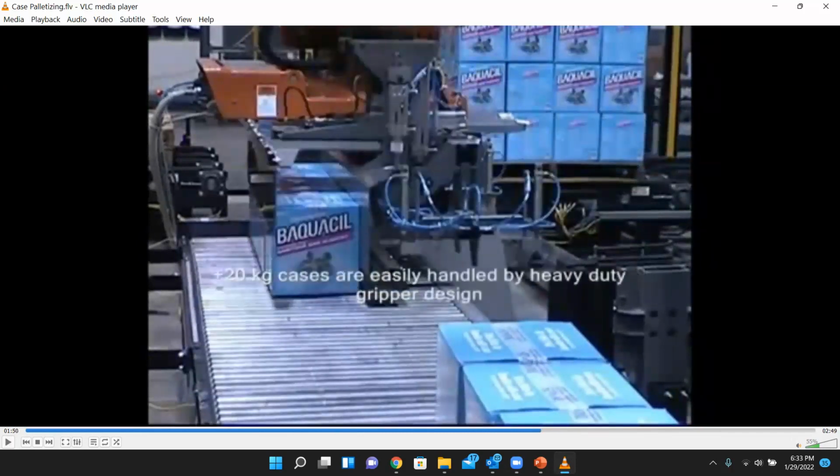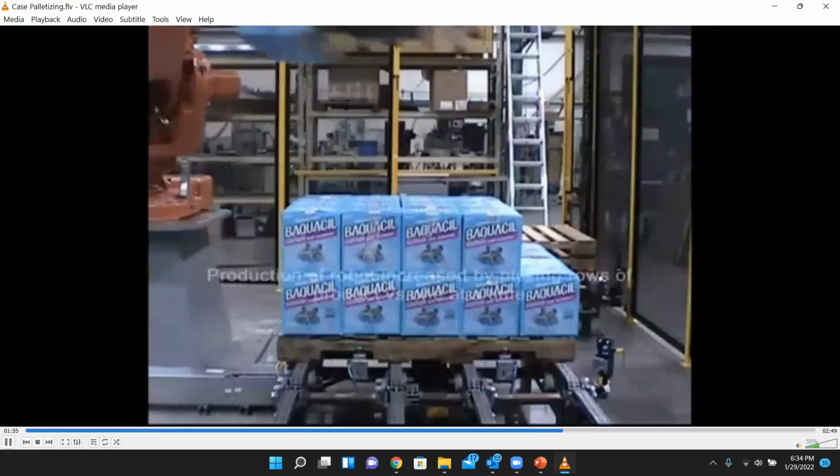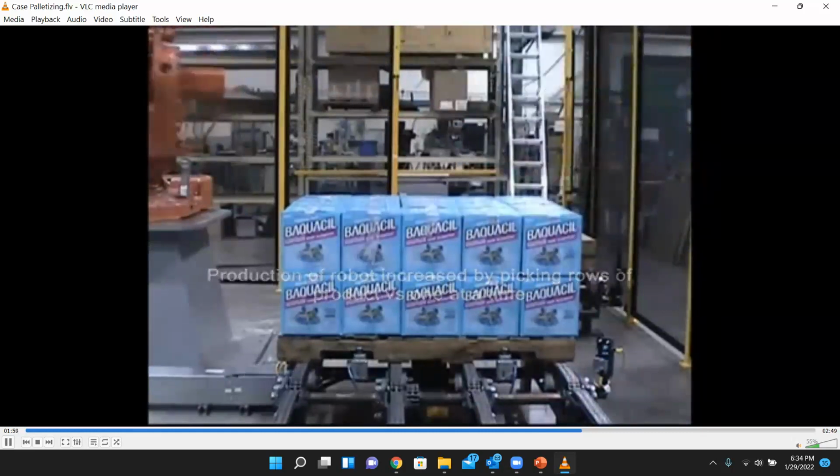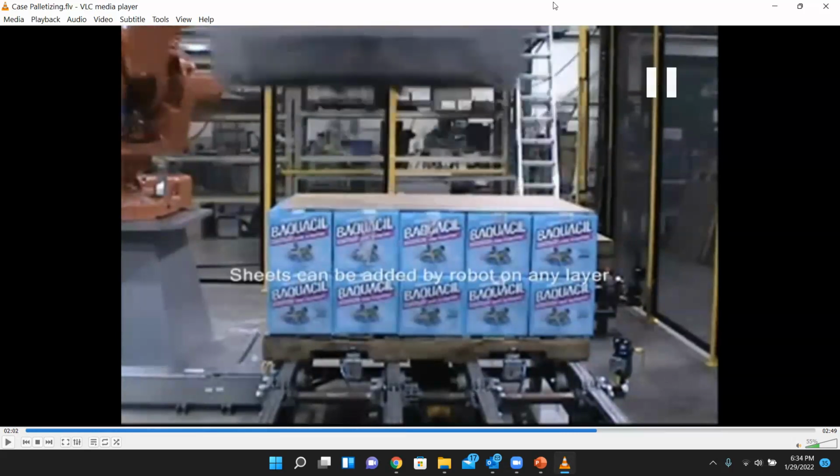So there you can see this end effector is designed to align all the boxes before the boxes are gripped. You don't have to make things unnecessarily complicated. With a gripper like that, with a little push, you can align all of the boxes perfectly. Now, this is very important. After every, say, 2 layers of these small objects, you need to put another board, because it is not good to keep on piling these boxes too long. So hold on a second.